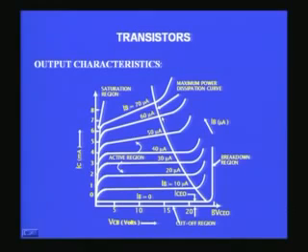IC max and VCE max product gives you the power rating, and that is basically a rectangular hyperbola, and therefore it will come something like this as shown in the picture. So, that is the limit beyond which you should never operate your transistor. This is the region in which you should make your transistor work for you for different applications, and this is the output characteristics of a transistor. In this case it is an NPN transistor with common emitter configuration.